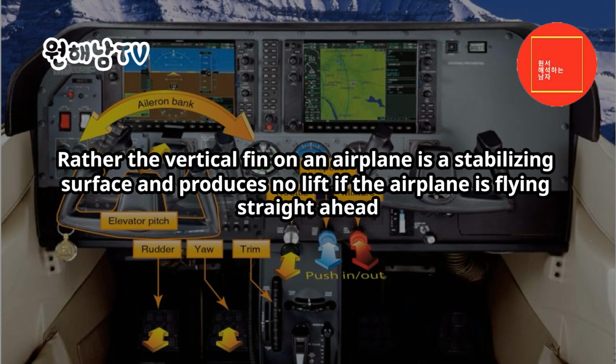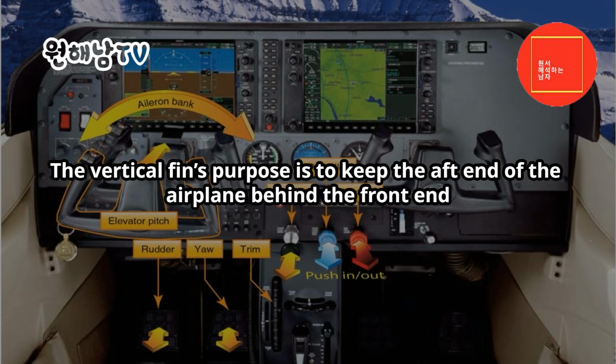The vertical fin on an airplane does not produce lift. Rather, the vertical fin on an airplane is a stabilizing surface and produces no lift if the airplane is flying straight ahead. The vertical fin's purpose is to keep the aft end of the airplane behind the front end.